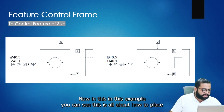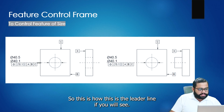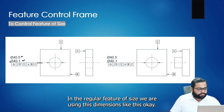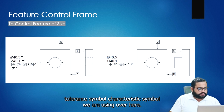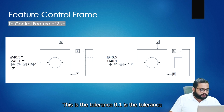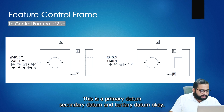Now in this example, you can see how to place geometric symbols in the engineering drawing. This is the leader line, placed on a regular feature of size, where we use these dimensions. This is the positional tolerance characteristic symbol. This is the tolerance, 0.1. M under a circle is the modifier, maximum material condition. Then this is the primary datum, secondary datum, and tertiary datum.